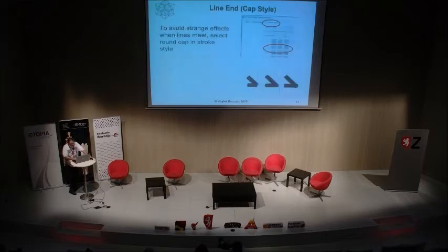Lines. What is important is line style. There are 3 different types of the line style. It is shown the cap style. You can see in large drawing what happened. This strange effect we would like to avoid in case of the sharp end of the line. So I always use round cap that could be set in the Fill and Stroke tab and stroke style for a line.